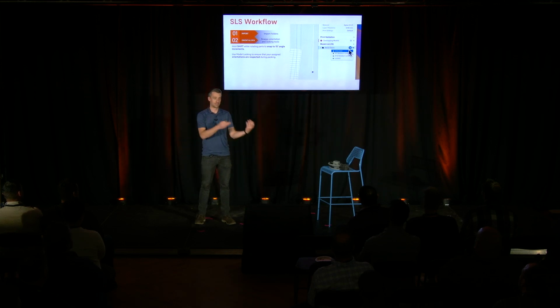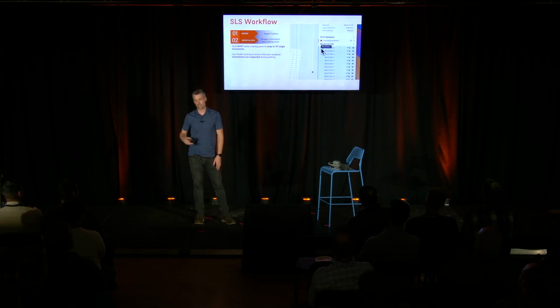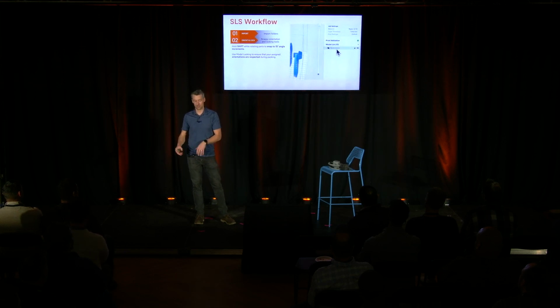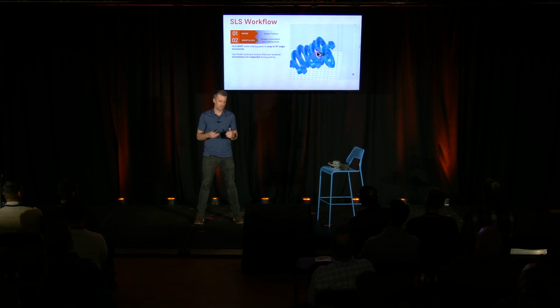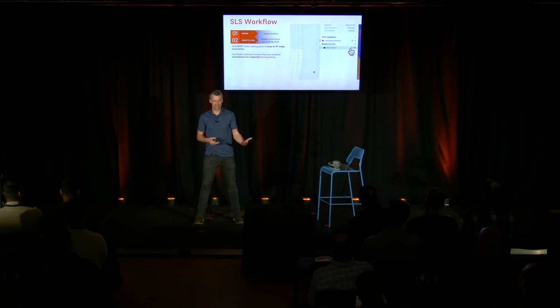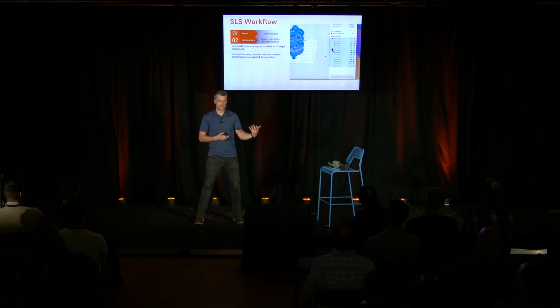So when packing happens, the packing algorithm will take that and use it as part of its constraints for putting these parts together to get you the most efficient packing job possible. That packing algorithm is one of our great things. We'll talk about that in a minute, but these rotation, snapping, and model locking tools aren't used by some users because they're less discoverable, but it's a really important part of the workflow, especially on SLS. A few different use cases here.